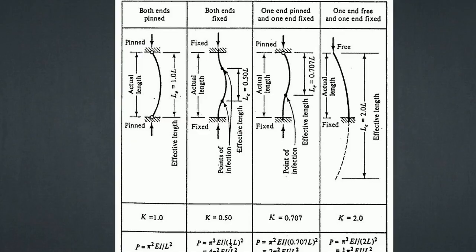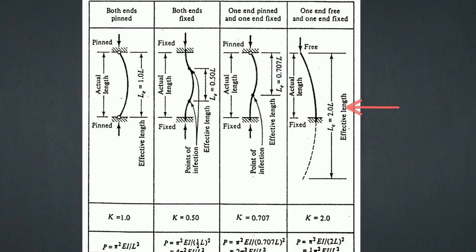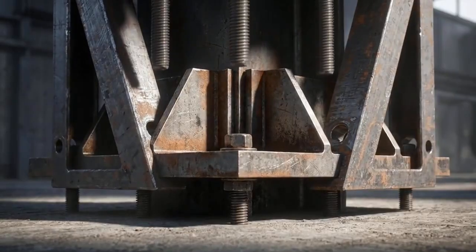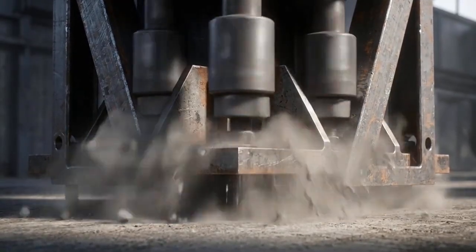This diagram outlines boundary conditions. The first panel shows a pinned column. Its effective buckling length equals its physical length. Rigidly fixing both ends cuts that length in half. Conversely, leaving one end free doubles the effective length, bowing under half the load. Ultimately, the security of those boundary anchors dictates the column's stability far more than its total physical height.